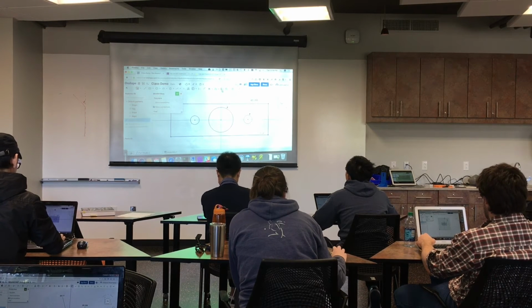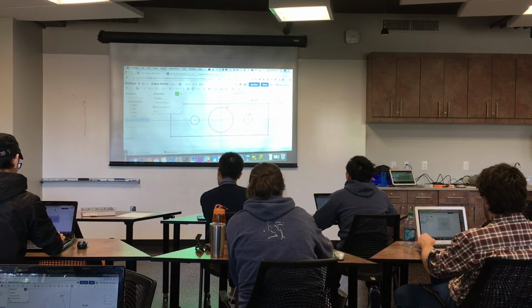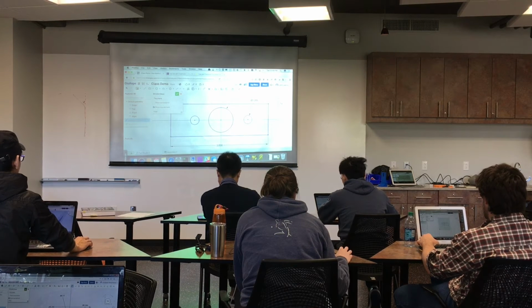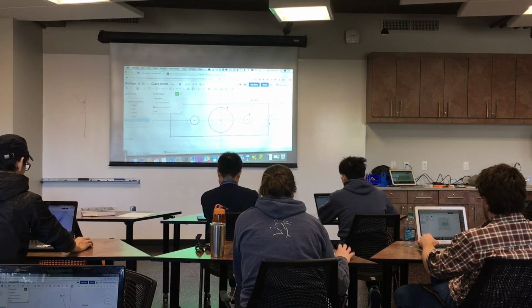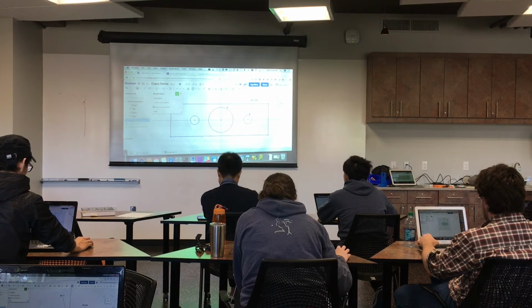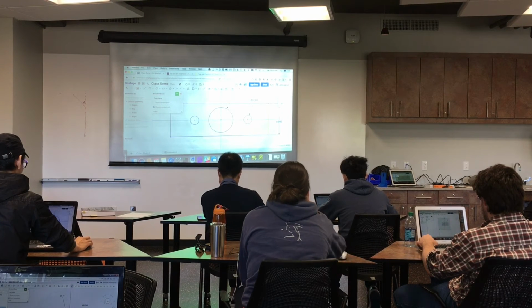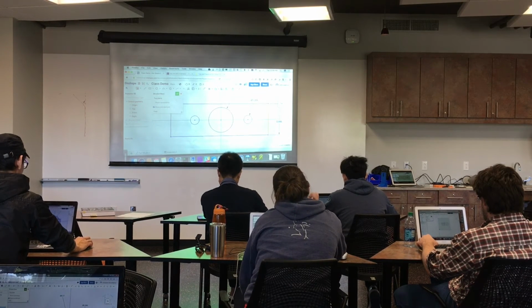All right, go back into my dimensioning tool. Now we could dimension, like you can click this line and say exactly how long you want that to be. We could click here and specify that. But design intent, I want this to scale. If I change that hole in the center, I don't want to have to go back and update all of these dimensions.